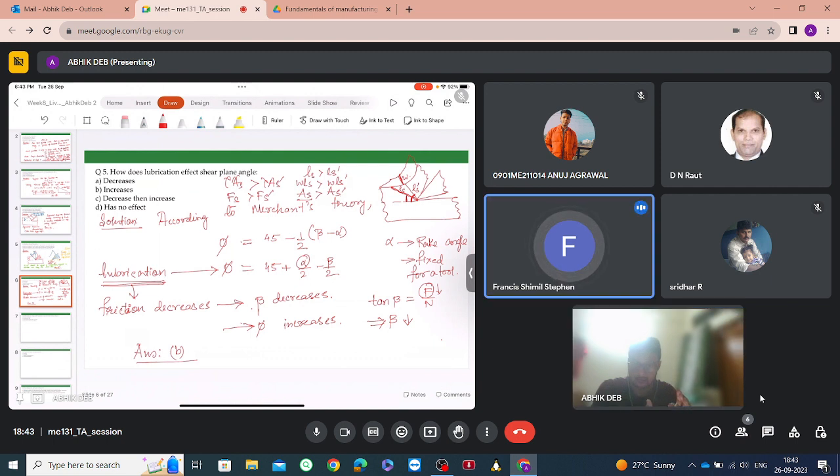Okay, sir. So during a single operation, it won't be changing. Yeah, in most single operations, or even repetition of operations, we would like to keep the rake angle fixed for a particular turning operation on different phases. If the turning operation itself is changing, or a different kind of turning operation is required, then obviously we will have to change.